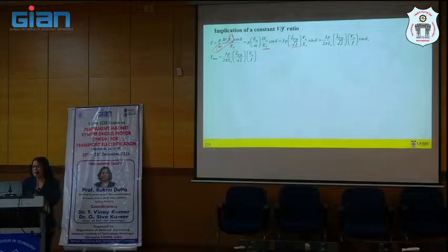So let's expand that synchronous reactance as 2 pi f Ls, right? This frequency component, we can then make it as a ratio of V over f, and keep the 2 pi and Ls part out of it. So now if we look at it, it will remain constant even though we are changing frequency, or even though I am rewriting it differently, right?